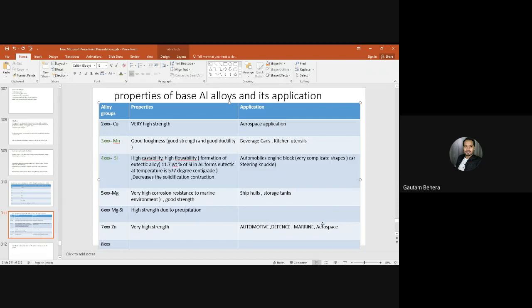If you look nowadays, the new generation Audi cars, as I've been saying many times, are basically made up of full aluminium. There is no trace of steels. They are made up of these 7000 series alloy groups of aluminium. And 8000 series has other alloying elements. Depending upon the alloying elements, they have different applications, like aluminum lithium, which is used in making aeroplanes in the aerospace industry.